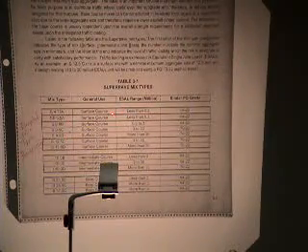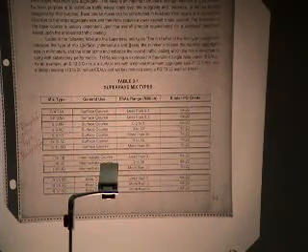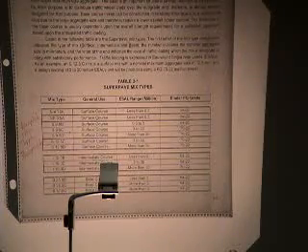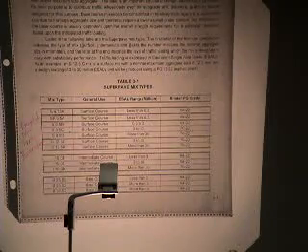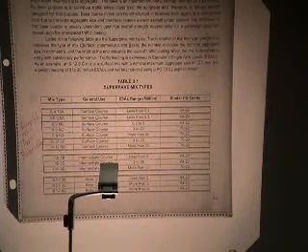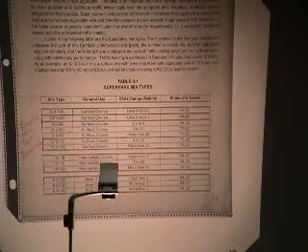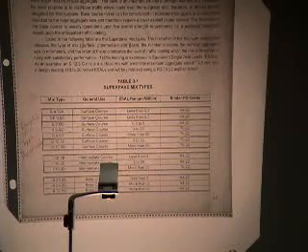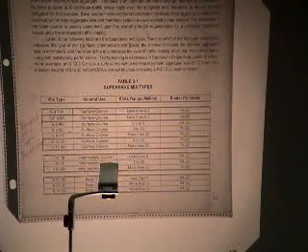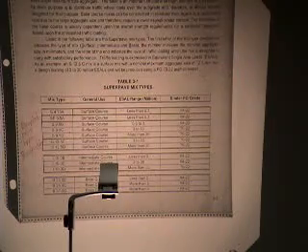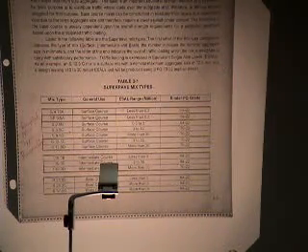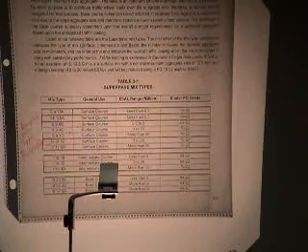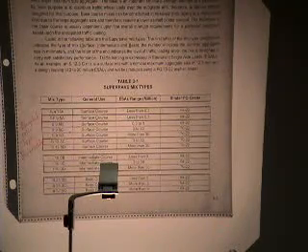As I say, there's 4 levels. A is the lowest level. A level mixes are designed primarily for your low traffic, say 2-lane secondary country rural roads, whereas B level is for higher traffic, maybe your lower primary routes, low traffic primary routes.